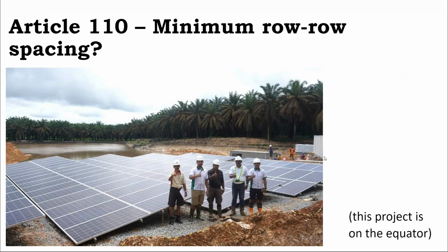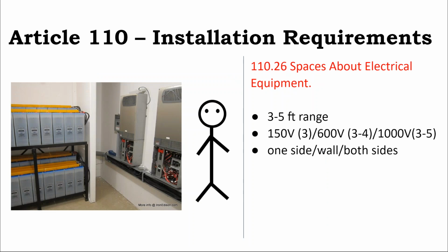Now, you might even say, what does that mean for spacing around the solar panels themselves? What I can say to that is I guess the whole array is considered one unit, because there's not 4 feet of space between the individual rows on solar arrays. I like it when there is space for accessibility, but the standard is to cover most of the roof and only have walkways every 120 feet.